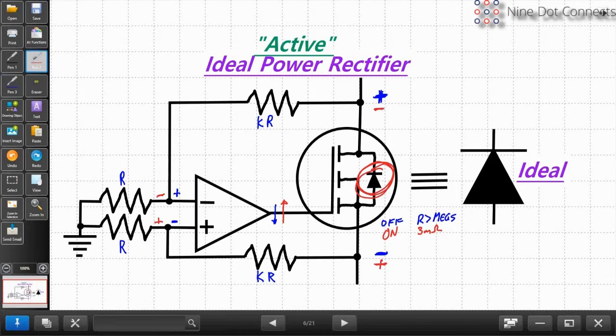Again, ideal rectifier. Where are these especially useful? Well, low voltage circuits. Where are there low voltage circuits? I'm sure some of you have seen 1.2 volt regulators and other things. Another very key place it's coming up is in solar, where the typical voltage on a solar cell may be 0.55 volts at the maximum power point, and possibly 8 amps in full sun. So you end up with needs for very high currents and not much drop in the reverse direction.